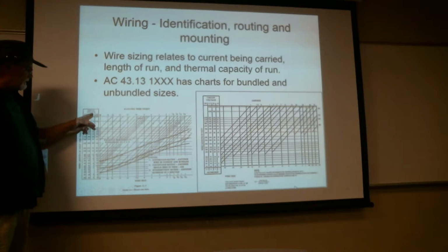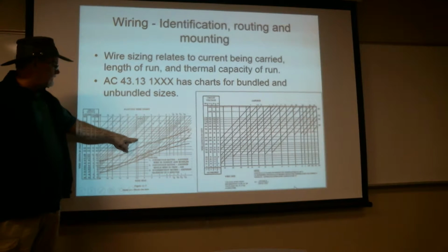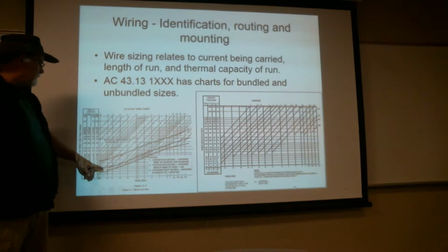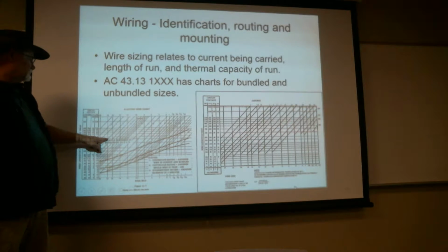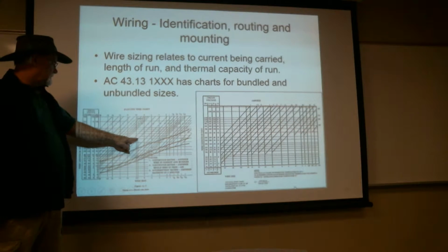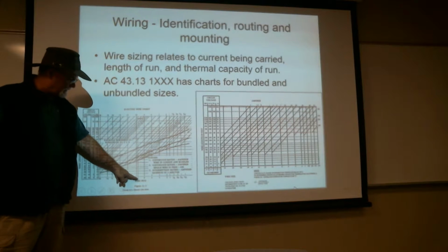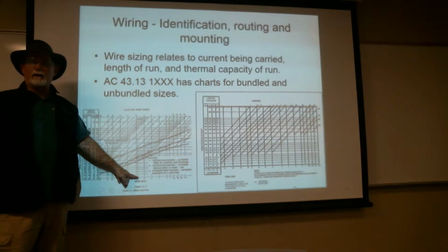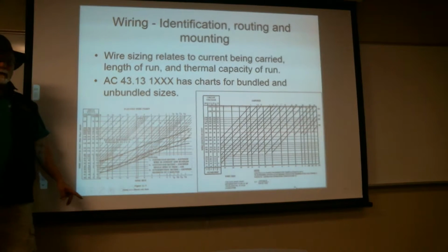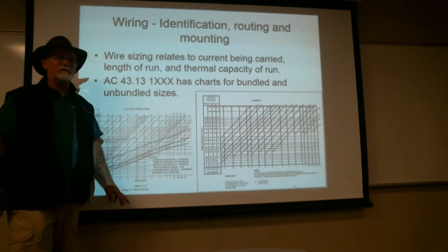So at 50 feet, 24 volts, whatever it was, 52 feet, I'm going to go out to the approximate current rating. And again, I think I've lost it here. I keep seeing 15, but 15 is here. So it actually looks like 18 or so. Then we're going to come down to here. We cannot use 10 because 10 is too light of a wire. We'd have to go up to an 8 gauge. We'd actually go to a 9 gauge, but they don't make it. So we've got to go to an 8 gauge.